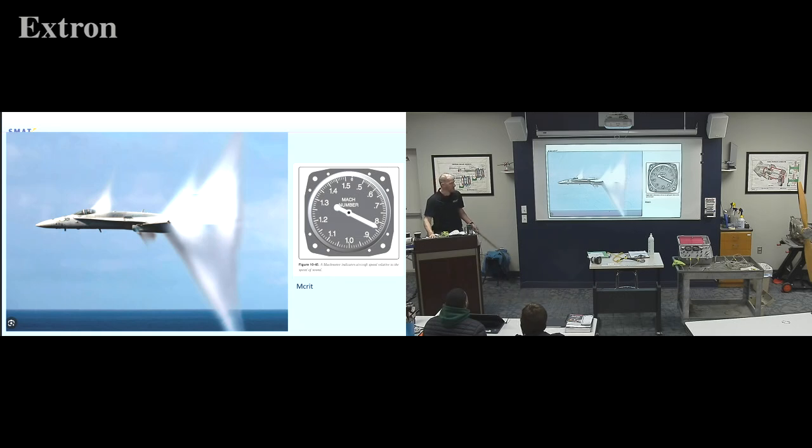So your Mach meter typically is going to be accurate in the air density that you're flying in. So just an FYI, if you're looking at your Mach number, you usually don't have to make any adjustments for air density because it's already pulling all that info into it to say where am I at. But don't fly faster than the speed of sound, okay? Everybody got that?